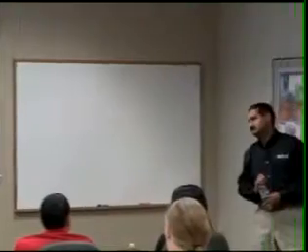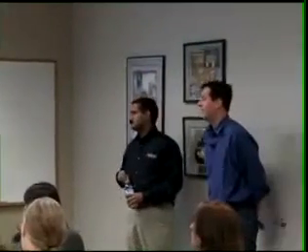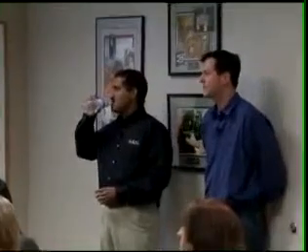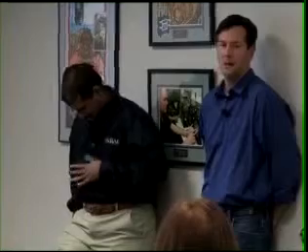So let me pose the first question to Jan. Not sure if you mentioned this, but how do you extend the range on your wireless devices? Okay, so on the range of the wireless devices, we've got several. The ones I was focusing on were our MeshGuard products. Typically we spec it out to be 1,000 feet or 300 meters point to point. The beauty of a mesh network is that all the detectors can either talk to each other or talk directly to the controller.